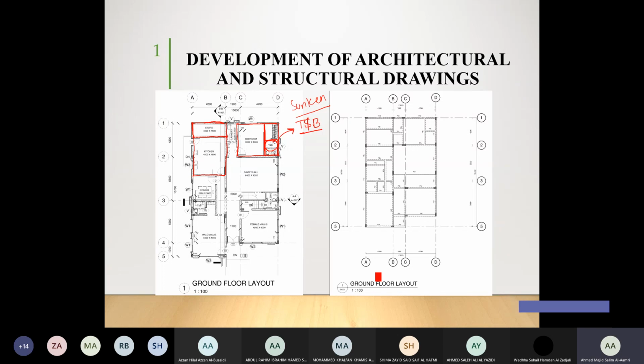Whenever there is, see here, we have a beam, but we don't have a wall here. Can you see? We don't have a wall. Normally in structural design and structural analysis, we prefer to keep the frames going fully from the beginning till the end. Plus this particular slab, the designer at that time might consider it to be big, so he placed a beam. It's not necessary for you to place a beam here, but if you want to, you can do it.